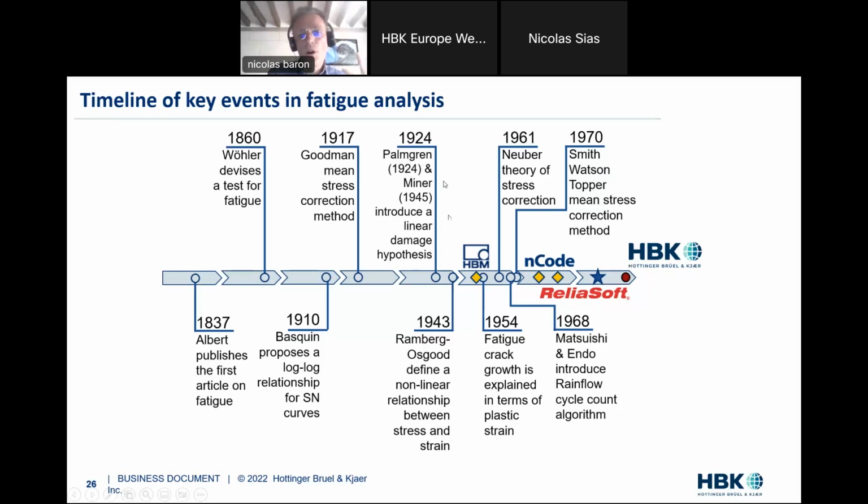Then big names also are Miner, Palmgren-Miner. They introduced the rule that we will use, and we will explain in more detail what the Miner rule is. The Miner rule is basically the rule that's used for making fatigue calculations in our design.